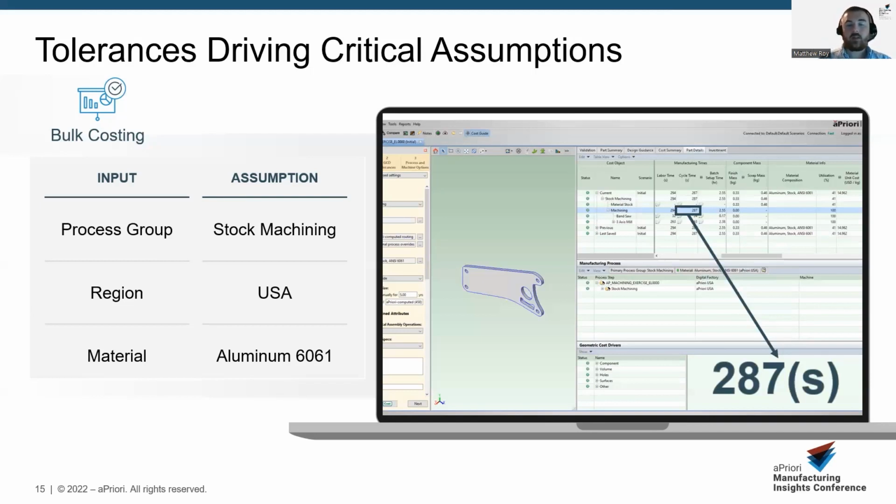With that said, we can write very, very simple logic so that instead of automatically defaulting to secondary and specialized machining to accommodate a tolerance, based on a tolerance band or threshold, we can automatically apply additional finish passes to certain features. Now, the reason why it's included here in this presentation for efficiency is because number of finish passes is something that a priori always assumes to be one and needs to be overridden feature by feature.